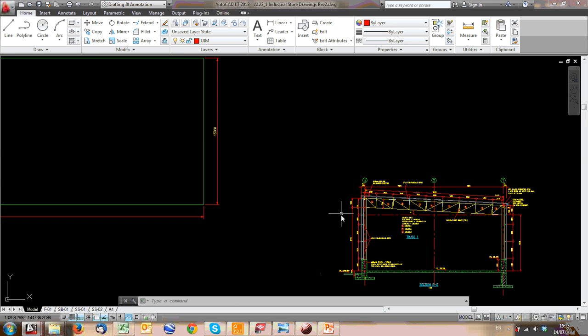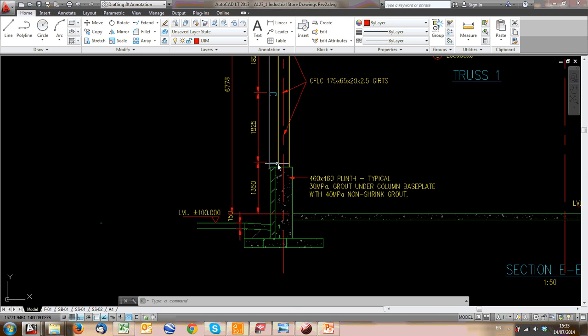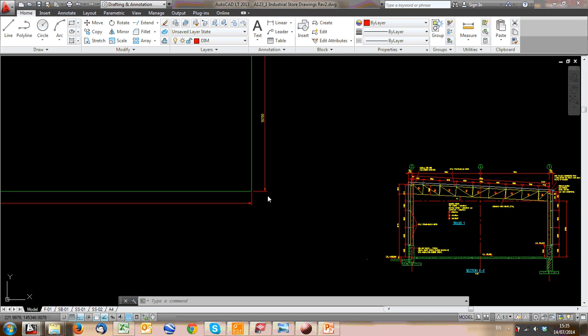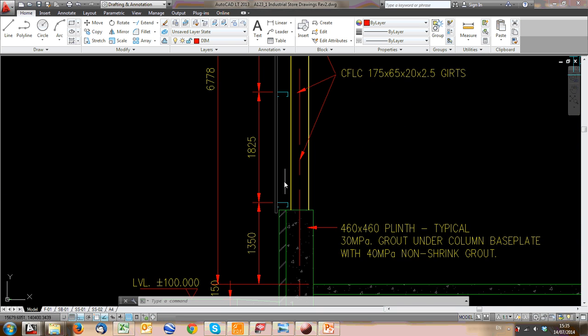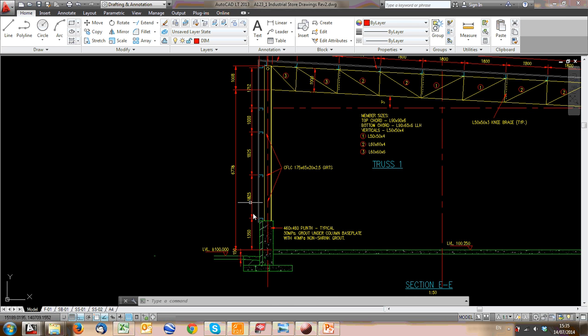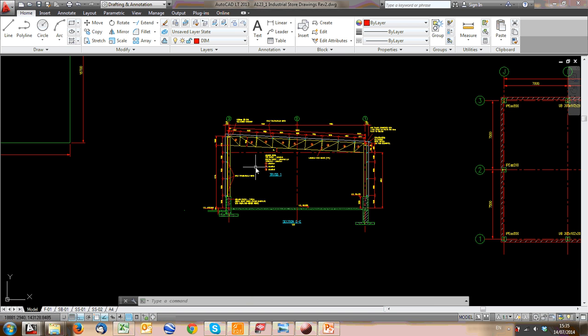is your sheeting line, because as you can see, the center of your column is a bit back from the edge of the building. And if the client's given you a dimension to the edge of the building, you need to know what is the dimension between your sheeting and your building. Now, in some projects, you might just be given the grid lines directly. If there's an architect who's been involved already, often you'll just get given the grid lines, or sometimes the client has certain requirements, so he gives you grid lines.